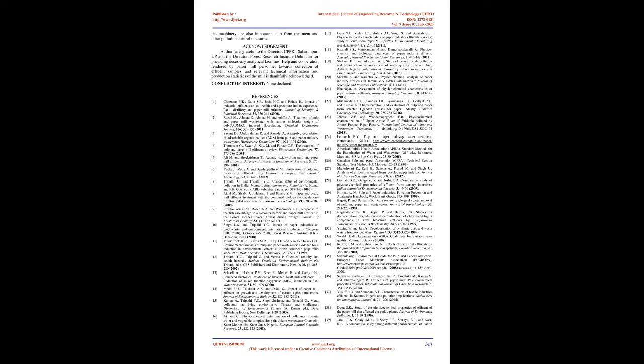The turbidity values of effluents from all the four units are in consonance with respective TS, TDS, and TSS values. Higher turbidity retards light penetration in the water, thereby reducing photosynthesis and production of dissolved oxygen. Effluent turbidity can be considered as efficiency measure of coagulation flocculation process of the unit. The results of turbidity measurement evidently suggest much higher turbidity in effluents of all processing units, and the values are greater than the WHO prescribed standard limits of 5 NTU, ideally below 1 NTU.